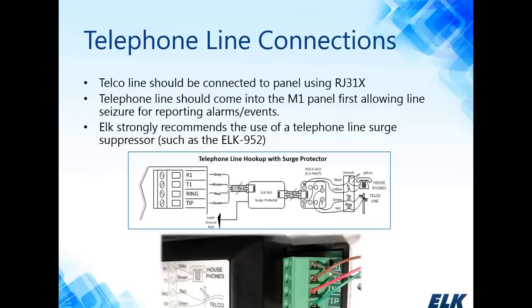Now the telephone line connections on the M1 in the upper right hand corner, this is hardwired landline copper telephone connection, standard, using an RJ31X jack. The incoming phone line should be the first thing that connects to the M1, and then the house phones downstream for proper line seizure so the system can communicate to the central station.